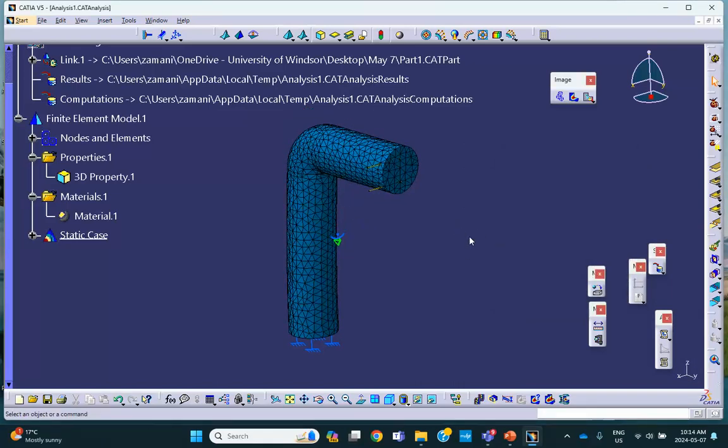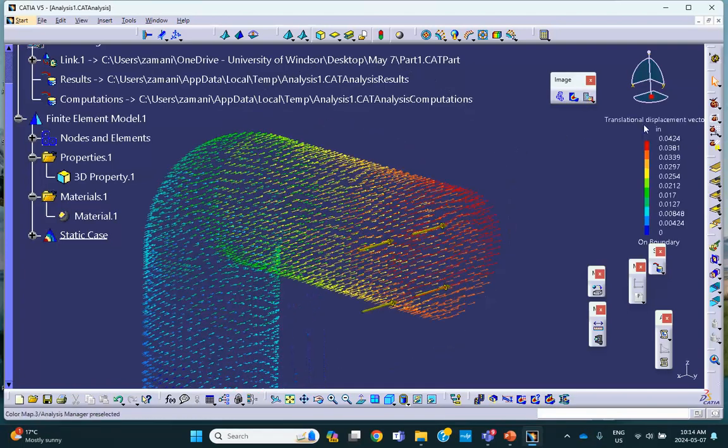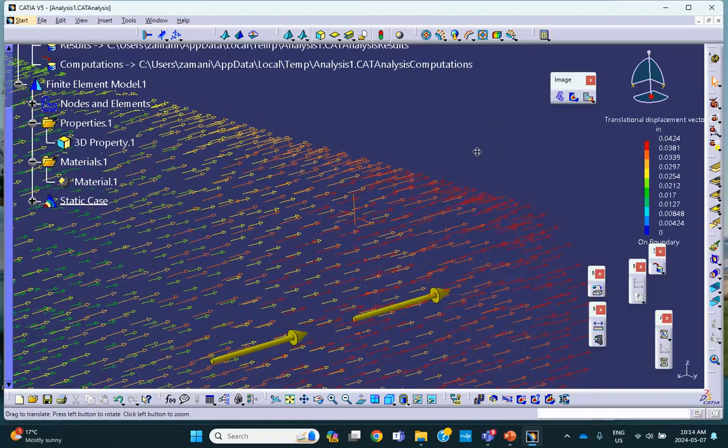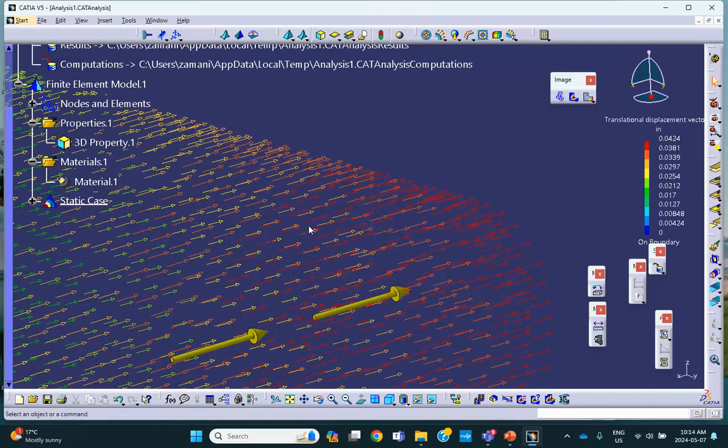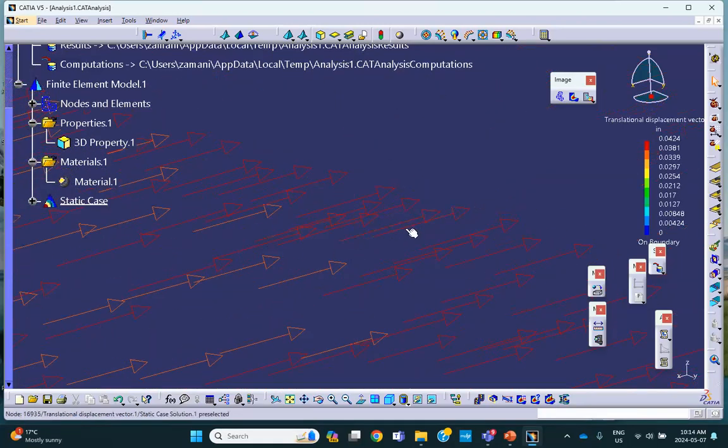So suppose that you want to know the deflection. So here, put the cursor there on this guy, says displacement. You click on the displacement, it shows you 0.024, okay? Now, what it shows you is all the nodes and the vector with three components, which give you the displacement of that node right there. So that means the node at this location has displacement in the x direction of 0.04 inches, negative, of course, and in the y and z direction of 0.0023 and 0.00123.